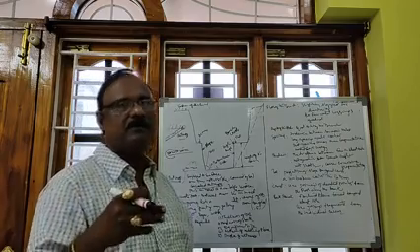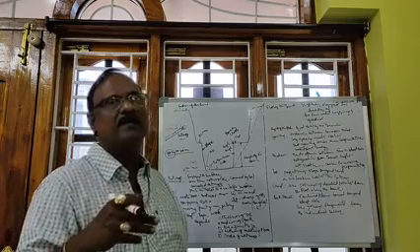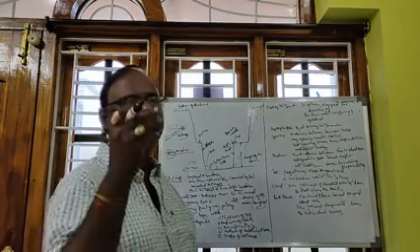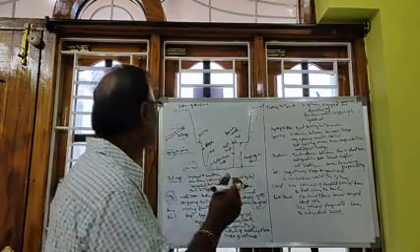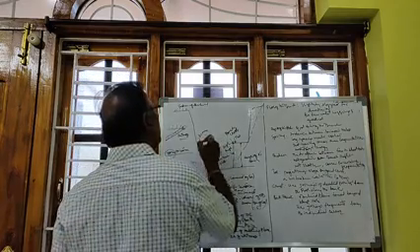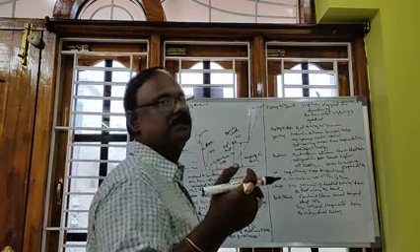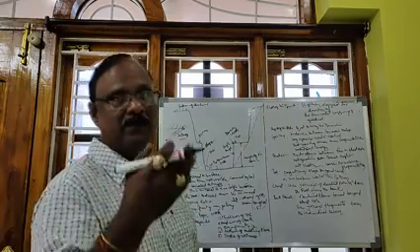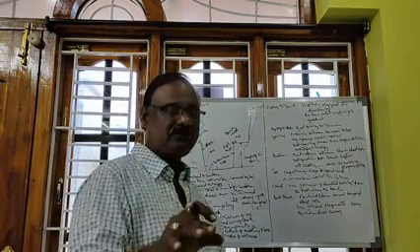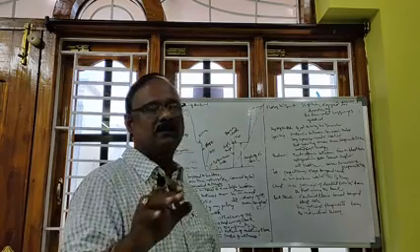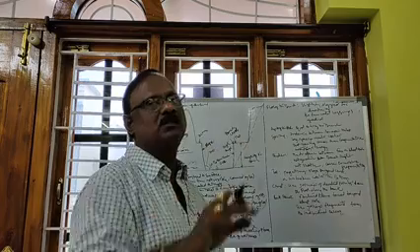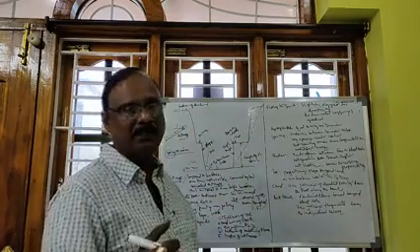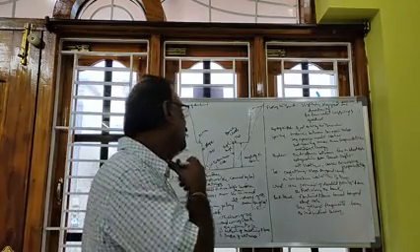For rock, suppose a granite rock is there, or the overburden is dolerite rock, an igneous rock. For igneous rock, the angle of the slope may be more than 45 degrees, even 55 degrees or 70 degrees also. It is very stable and strong. Failures do not occur to the slope. Why? Because stone has higher stability than the soil, than the alluvial soil.